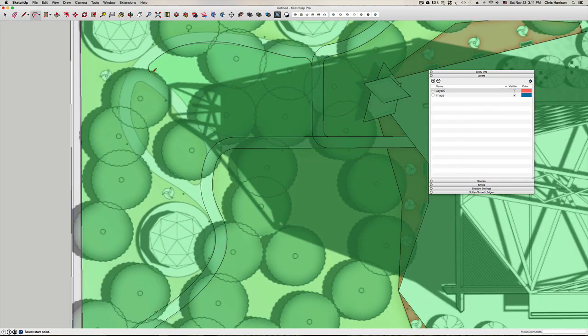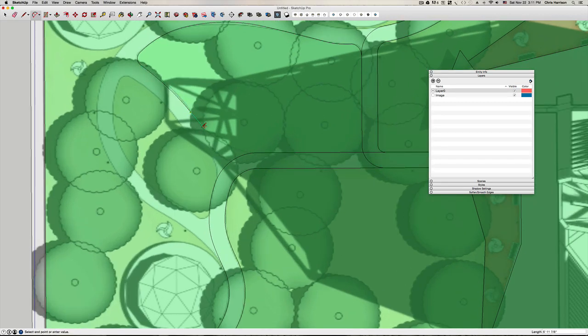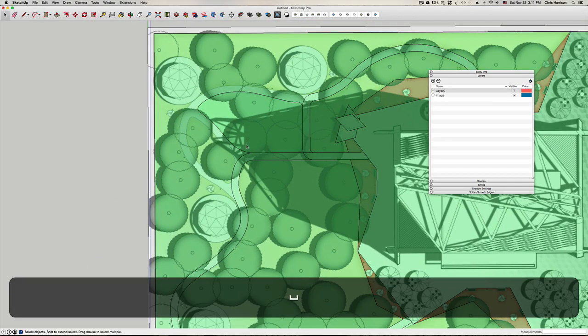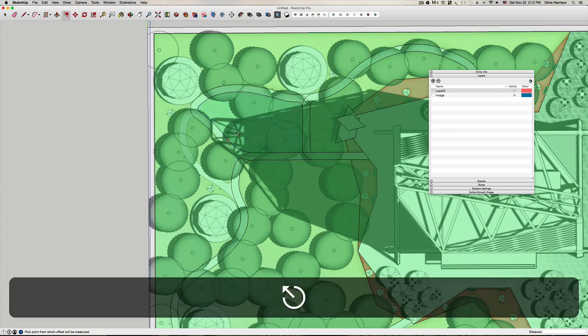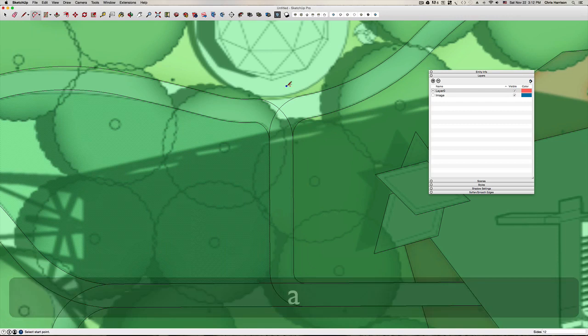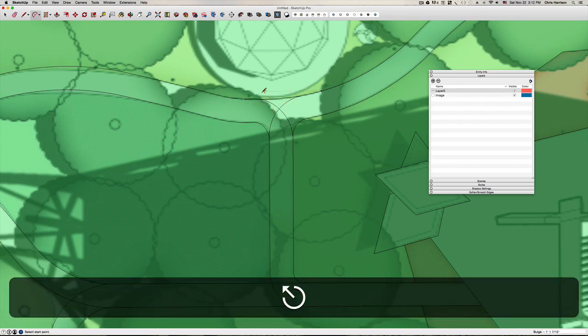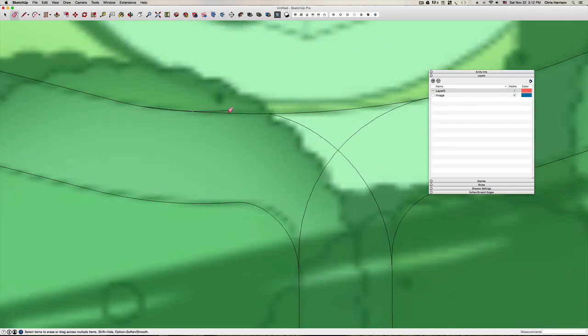Zoom in. Alright, that looks good. This time, let me try to deselect some of these lines. I'm holding Shift just to deselect them. I don't need that either. I'm going to try to just offset that. That's cleaner, 6 feet. So not as much cleanup work, and I'll continue that arc there, and there we go. And then I'll delete that extra line work there.